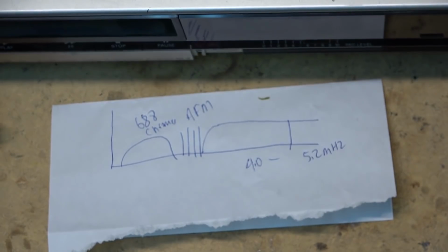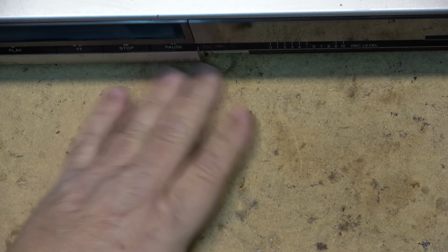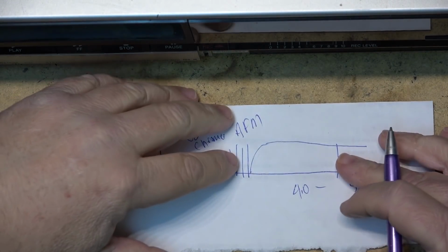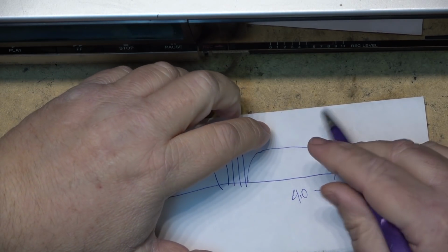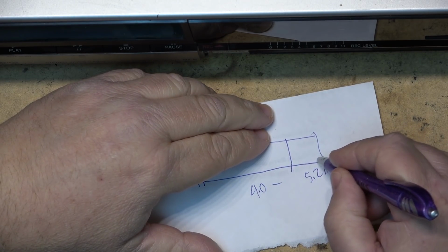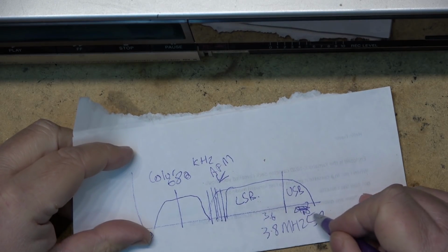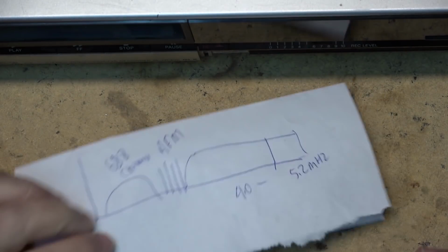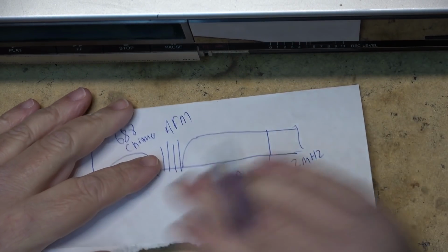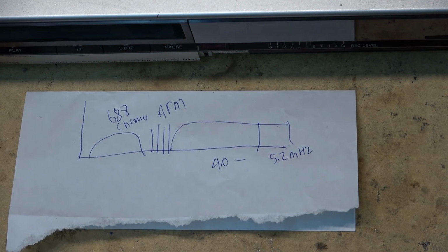And the reason they had that switch was that on playback, it also affected the bandwidth. If your playback circuit was expecting frequencies upwards to 5.2 megahertz, and the recording actually ended at 4.8, which is where the original Betamax was, you'd end up with some streaks and so forth in the picture because there was no information there, just noise. It would degrade the picture.